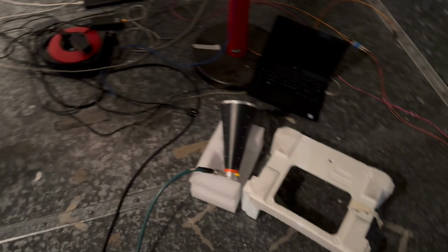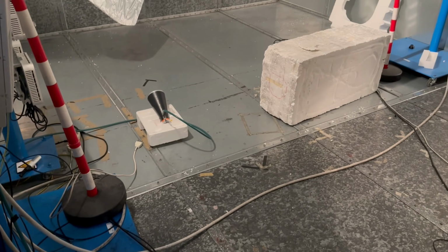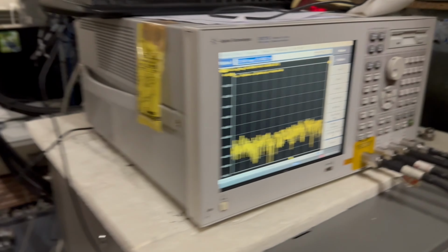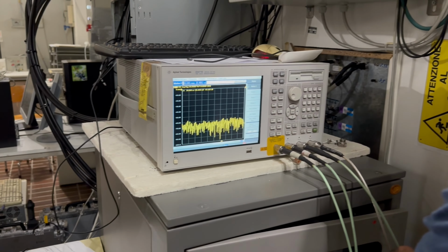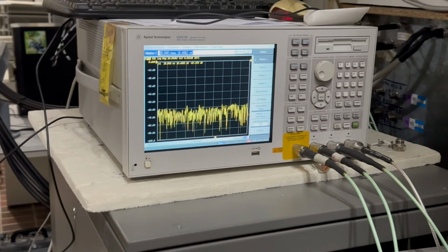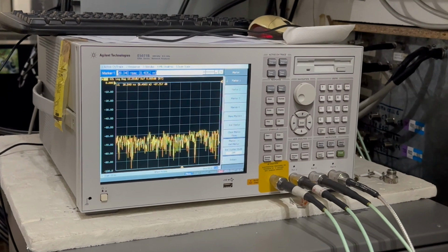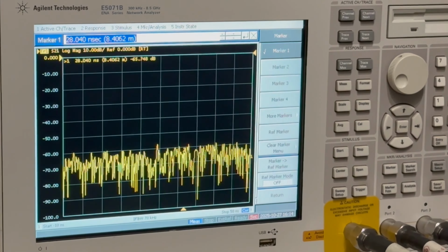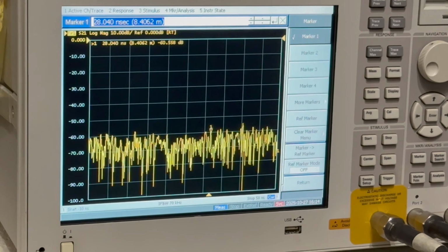So we now place both antennas away from each other and cross-polarized to reduce the coupling, and we repeat. So now you don't see a peak here. Now that's a realistic scenario, and if we start moving the steerer, we can see some peaks growing, and then decreasing depending on the steering position.